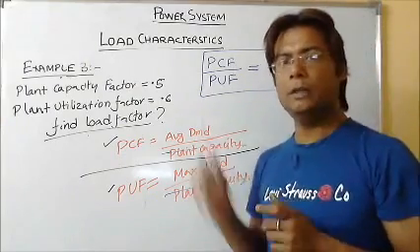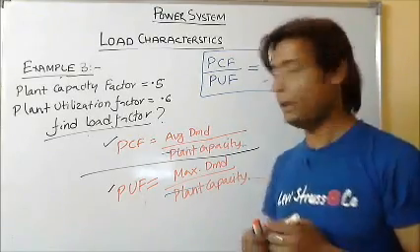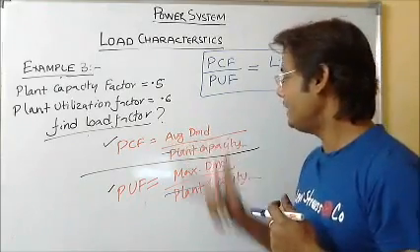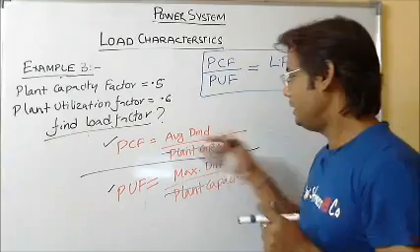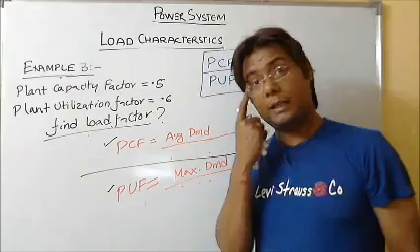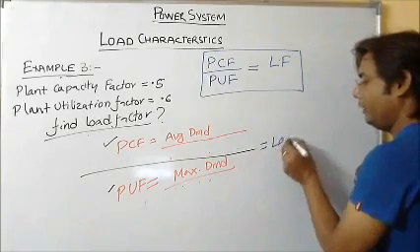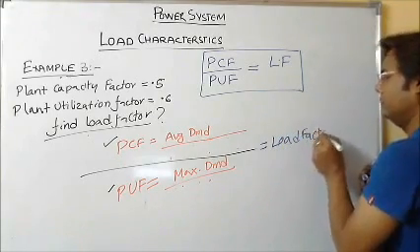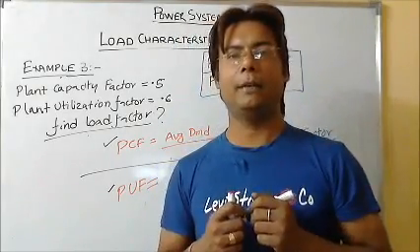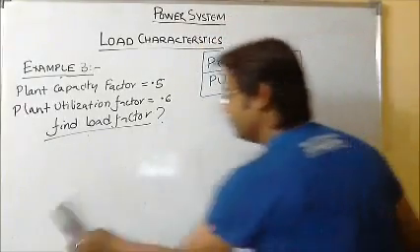What we understood as the load factor is the average demand upon the maximum demand, which is what remains, so it is equivalent to the load factor. So we can directly say that the plant capacity factor to the plant utilization factor is equal to the load factor.